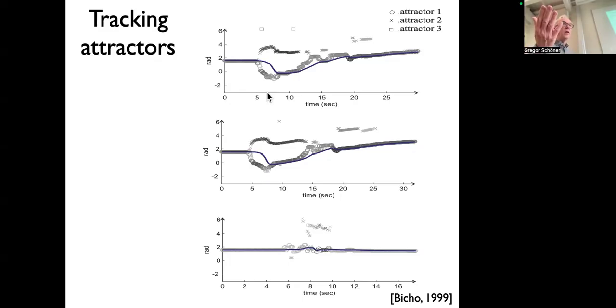We only need to know the position relative to the target, and then these 7 or was it 9 sensor numbers, and it will then uniquely determine the dynamics. And so you see here it has a single attractor, the target, I think, initially heading here toward the target, so the target will end up in that direction. And then this is where the bifurcation occurs as it approaches the wall. And you see it's a pitchfork. There's a repeller here in the middle. It's a very nice pitchfork, very symmetric.